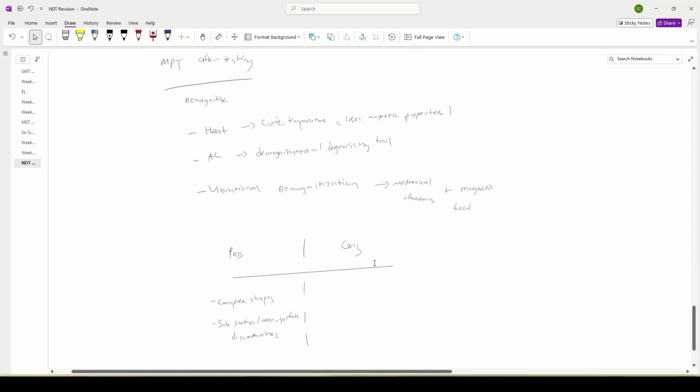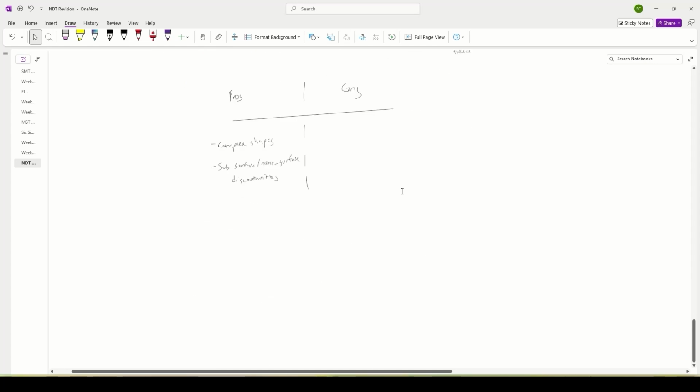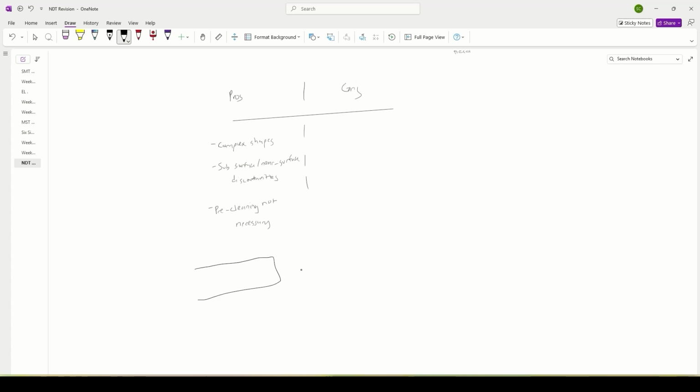If it's just parallel to the field, it doesn't do much. We are not using dye penetrant, where we actually inspect the surface. We are using magnetism to detect surface breaking defects. They are close to the surface but not necessarily on the surface itself. So if, for example, you have rust here, it doesn't interact with the magnetic field at all. It just cuts through.